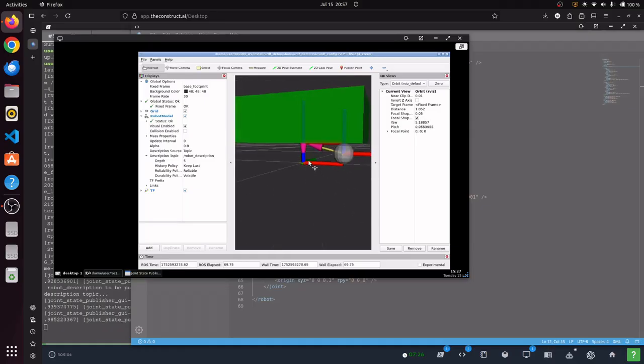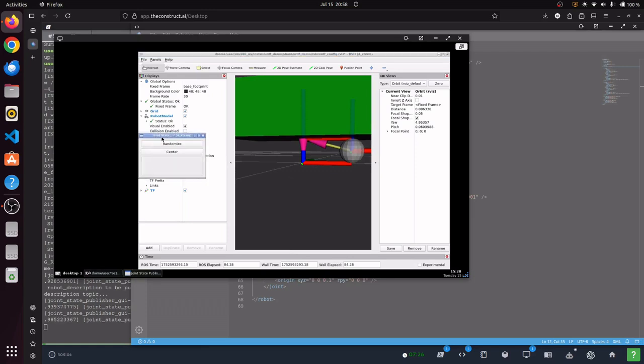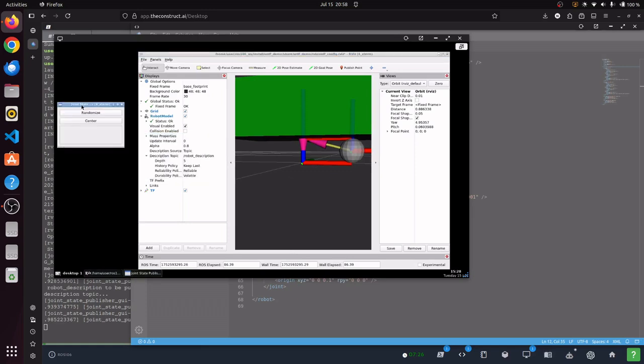These are the two links that you can see. This is the base link and this is the caster wheel link, and you can also see the transforms. For now these are fixed. So the joint state publisher is empty, but if you put revolute or continuous or prismatic joints in, you'll see sliders like previously.